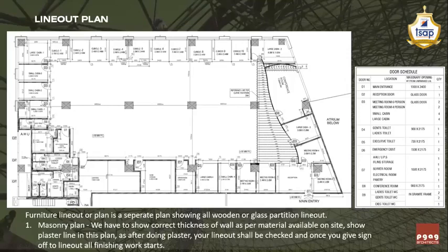The PCC or the screed which he puts onto the RCC slab to level the whole site with respect to the main level is sometimes 50 mm in some corner of the site and sometimes 75 mm in the other corner. So it is the contractor's responsibility to check the levels as per site conditions and to inform you if there is any discrepancy.